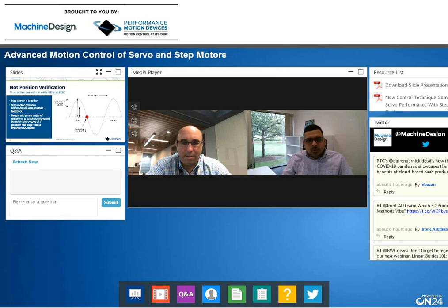So what we're trying to do is operate the stepper like a brushless at this operating point shown in red, with the encoder and position feedback, taking the FOC and treating it like a brushless motor, and doing all the adjustments that you would do with a traditional brushless. So you can have continually adjustable torque and phase angle. It gets you a better control setup at a lower price point.